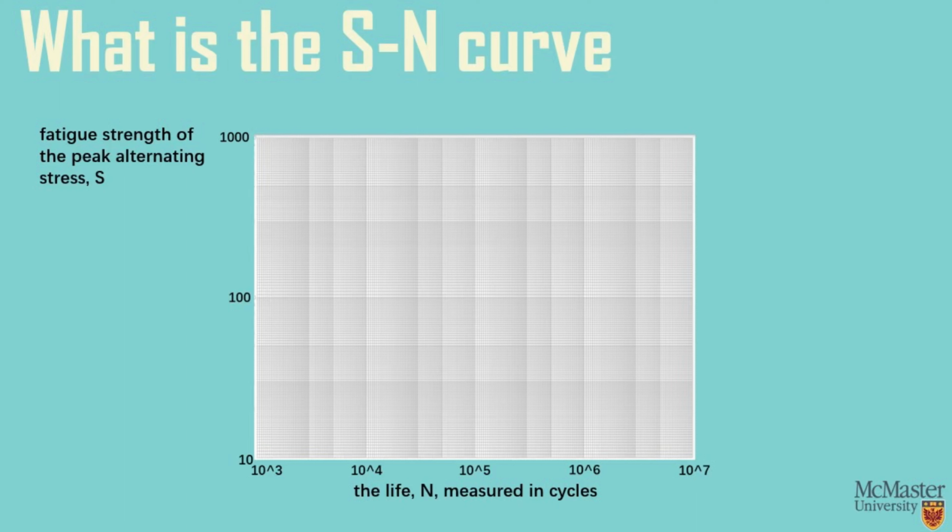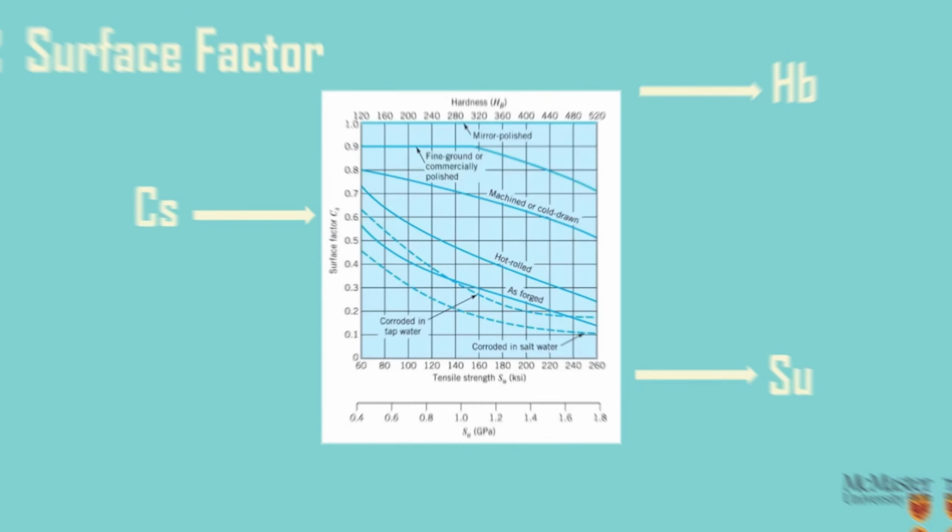Moreover, numerous tests have established that ferrous metals have an endurance limit, defined as the highest level of alternating stress that can be withstood indefinitely without failure. In the plots, the endurance limit is defined as S'n, where the prime indicates the special case of the standard test. The SN plot can be represented in linear, semi-log, or log-log coordinates.